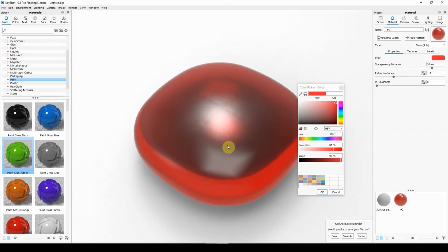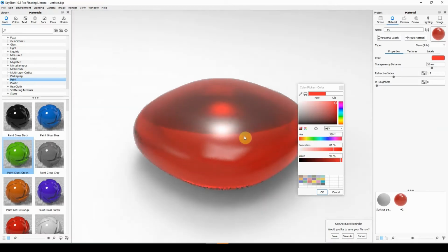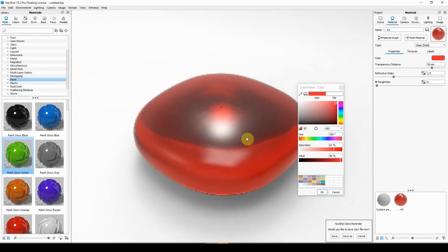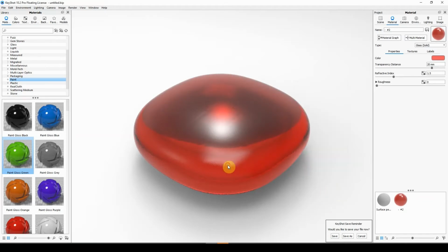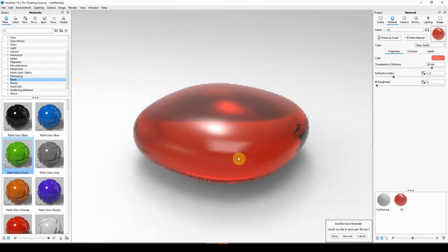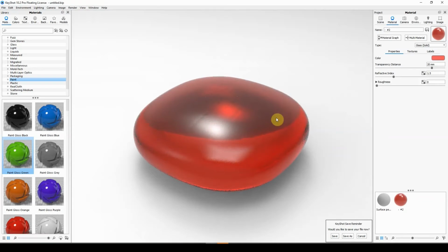Now what's important here within KeyShot and for 3D printing is to adjust the saturation bar until you just start to notice a change in the saturation color. So typically you can crank it down a bit and it will get to a certain point where you start to notice a difference. If you see at the back end of the model, it's started to become a bit lighter, so that's really where we want to leave the saturation for this model,